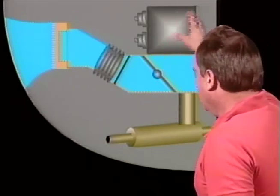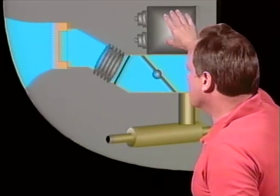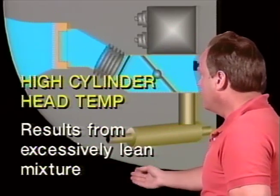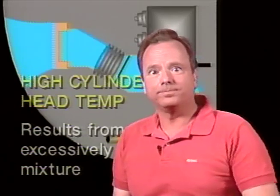Now, let's talk about leaning the mixture in an engine. Of course, on almost all piston aircraft engines, you can lean the mixture by pulling on the mixture control, and you reduce the mixture for thinner air at higher altitudes. So you have the same relative ratio at high altitudes as you do at low altitudes. And that ratio, of course, is by weight. Now, they're going to ask you what will happen if you have an excessively lean mixture. Very basic question. The answer is you could get high cylinder head temperatures from an excessively lean mixture, and that's just by pulling back too much on the mixture control at higher altitudes.